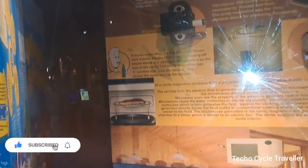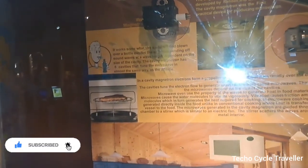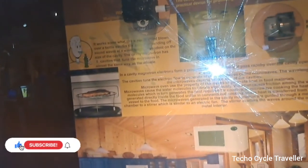It works somewhat like a whistle, where wind blown over a bottle excites the air inside, sending off sound waves at a wavelength depending on the size of the cavity. The cavity magnetron has 8 cavities that tune the microwaves in almost the same way as a whistle.